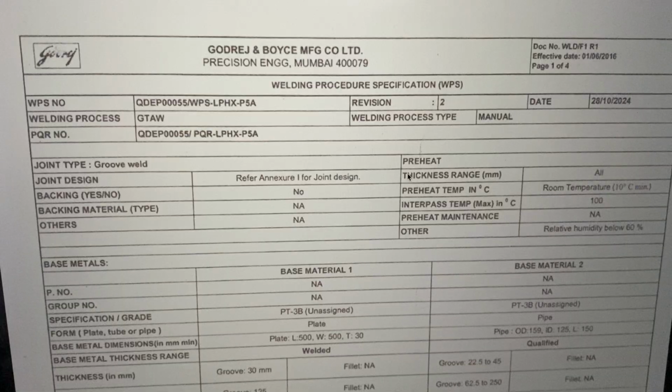And once the welding is complete, we have to ensure that the preheat temperature is retained for that time if there is no separate post heating. If there is a post heating, obviously we'll come to the post heating requirements as we move further. So this is as far as the joint type and the parameters, as far as the temperature conditions with which we are going to start working and start welding.